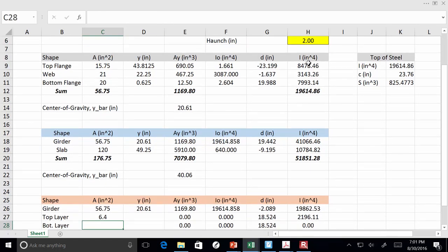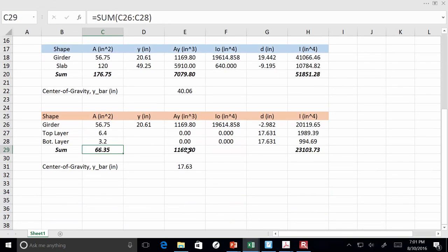For the bottom, I'm going to do something similar. I'm just going to copy and paste the whole thing. But I'm going to say 1/3. Make sense? So I've got this big lump of rebar on the top, big lump of rebar on the bottom, 2/3 on top, 1/3 on the bottom. Sound good? And that's it. The only thing left to figure out are these centroids. I'm going to keep it pretty simple. All right? So let's deal with the top layer first.